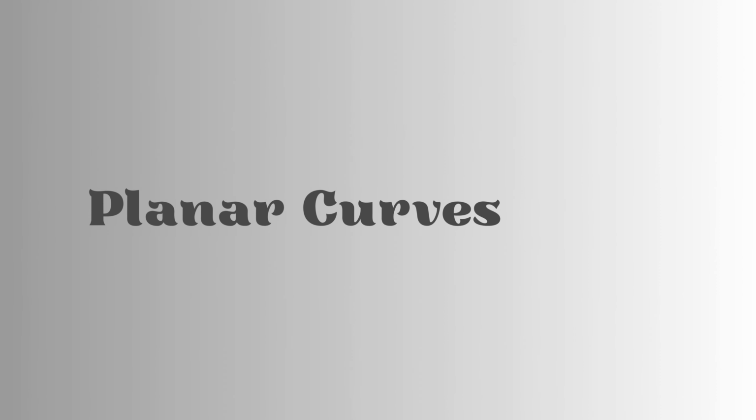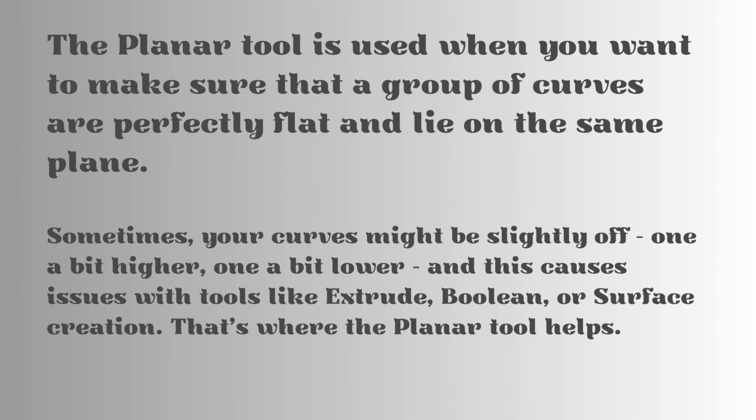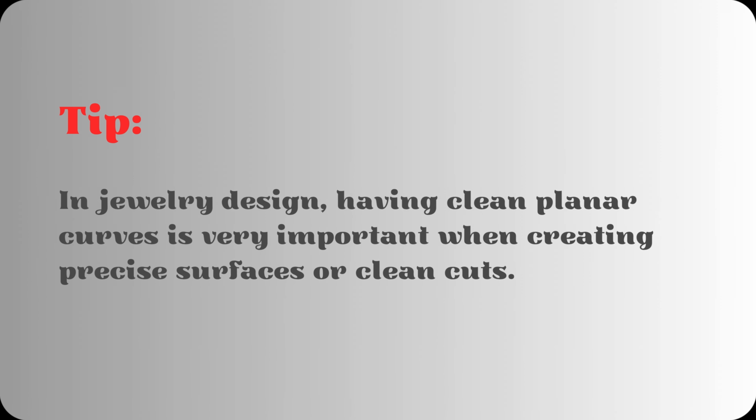Planar curves. The planar tool is used when you want to make sure that a group of curves are perfectly flat and lie on the same plane. Sometimes, your curves might be slightly off. One a bit higher, one a bit lower. And this causes issues with tools like Extrude, Boolean, or surface creation. That's where the planar tool helps. In jewelry design, having clean planar curves is very important when creating precise surfaces or clean cuts.